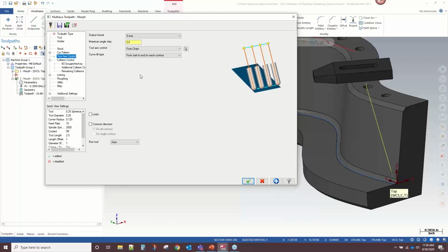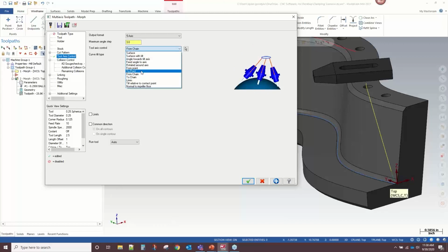So David asks, on your first example, can you use an offset drive surface? And does the drive surface have to be below the cutting surface? So I think you're asking about clean core methods, where you're pathing on an initial simplified surface and then offsetting to the final surface. And you can certainly do that with this style of tool axis control. So this is very simple to set up, but it's very powerful in that you're getting the exact angle control you want on the tool.